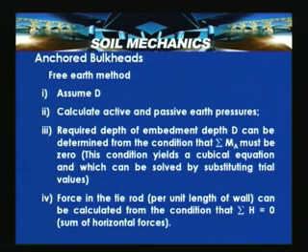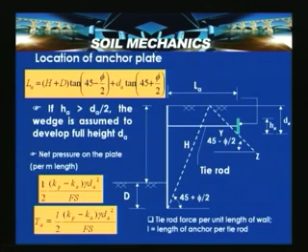We need to calculate whatever may be the passive forces, whatever may be the active forces, the net difference has to be compensated by these anchor rods or tie rods. And also one important thing as we discussed, the location of the anchor plate is very important.